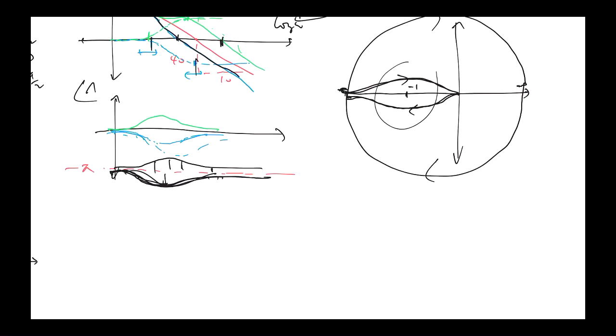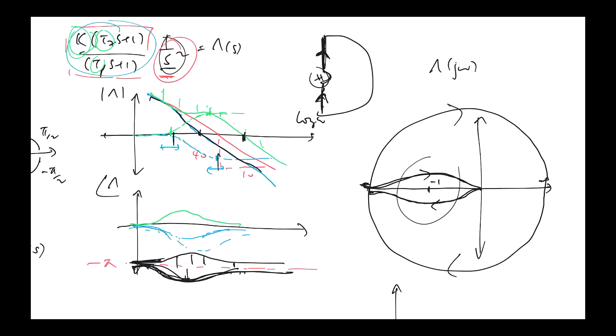So what happens to the Nyquist plot? Well, the Nyquist plot, in this case, will look like, we still start off at minus pi, so we still start off somewhere down here at infinite magnitude, right? Because at 0 frequency, 1 on the s squared, when s is evaluated at j omega and you set omega to 0, is infinite magnitude, but the phase is minus pi, so it's somewhere down here at infinite magnitude. We don't get quite the infinite magnitude because we put an indentation. We're never quite at 0 frequency. We're at plus epsilon or minus epsilon, okay?